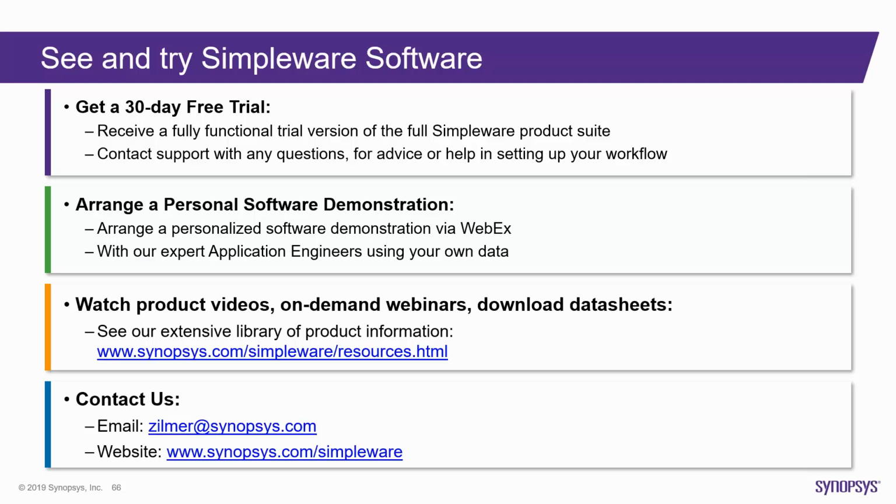And when you've made the 3D CAD, then you can mesh it inside the tool, right? And they have different kinds of finite elements. All the commercial finite elements are available inside the Simpleware. Once you mesh the thing, you can export to Abaqus as an input file, .inp file, right? Which is basically what you need to move ahead with the analysis in Abaqus. But they also have an interface to export in different file formats for other software too. So that's pretty much the workflow.